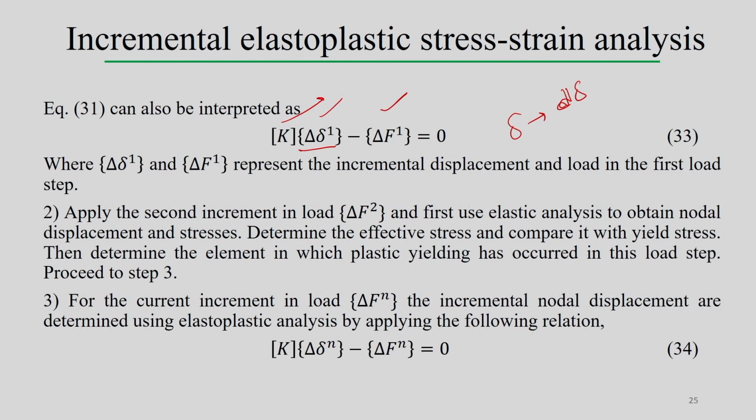Once we extract for the first load step, then we apply the second increment of the load. First we use the elastic analysis to obtain the nodal displacements and stresses. Therefore, it is necessary to consider first the elastic stress analysis, the elastic component. Then we find the effective stress value, determine the effective stress, and compare it with the yield stress value.